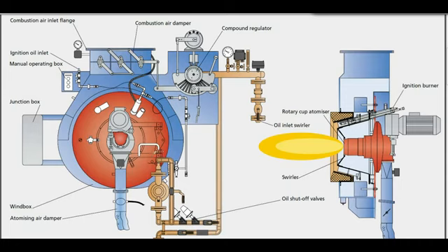Through the hinge of the door, the oil enters the main burner, and thus it reaches the combustion chamber or the furnace. And let's see the pilot fuel system or the pilot diesel oil line. From the igniter pump, which is usually located in the purifier room, the diesel oil comes through two manual shut-off valves, and then with a flexible hose it enters the pilot burner. And the pilot burner also has two electrodes which ignite an arc under high voltage, and there's a cable which is going to the junction box from here.